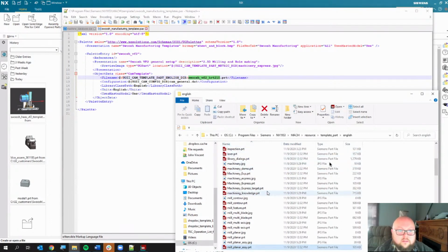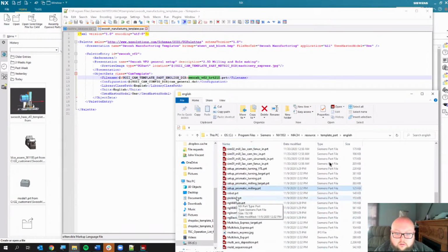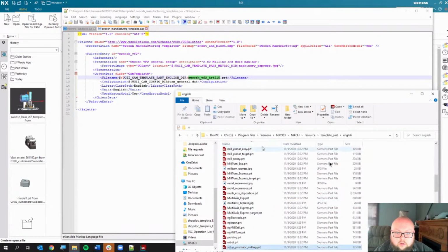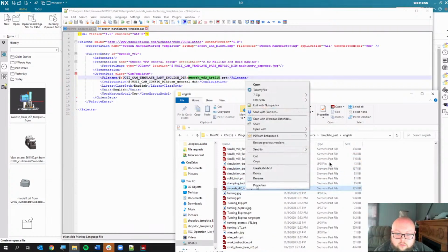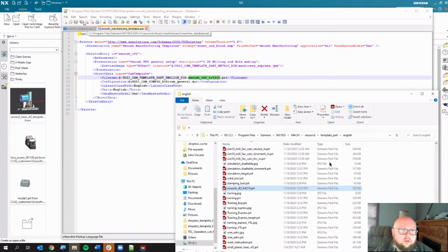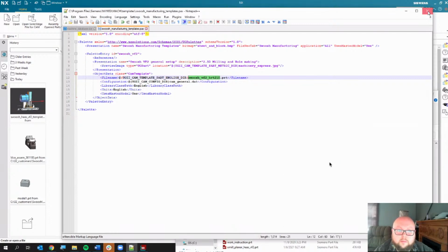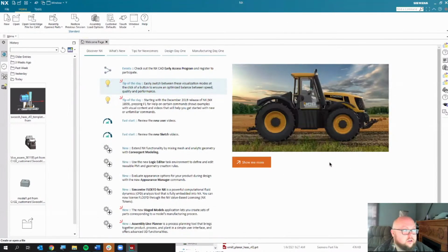So, all right, that's the next step. We have a template file now. We haven't really done anything with it, but that'll be our next steps. So let's see here. There we are, swoosh VF2, HRT210. I just want to check the properties on this file. Yep, I'm going to have to uncheck read only, so we have the ability to modify that now. And I'll go ahead and press OK. And I'm going to go ahead and close my XML file. We shouldn't need this again. I do have to, once again, close NX and relaunch it. So I'm going to go ahead and do that right now.